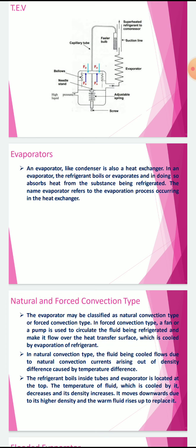Coming to the types of evaporators. In an evaporator, the refrigerant boils. Actually, an evaporator like condenser is also a heat exchanger. In an evaporator, the refrigerant boils or evaporates, and in doing so absorbs heat from the substance being refrigerated. The name evaporator refers to the evaporation process occurring in the heat exchanger.